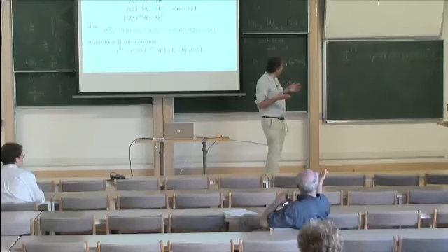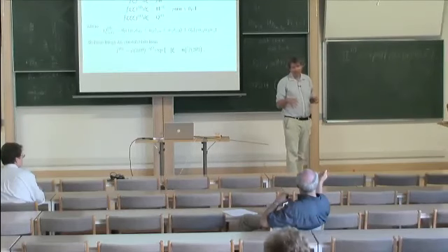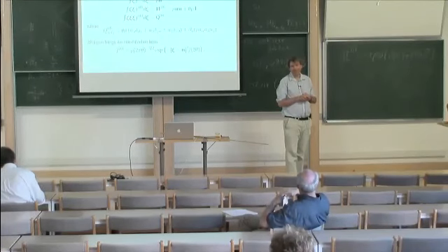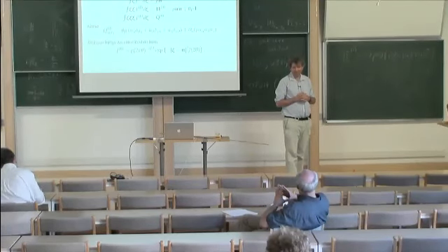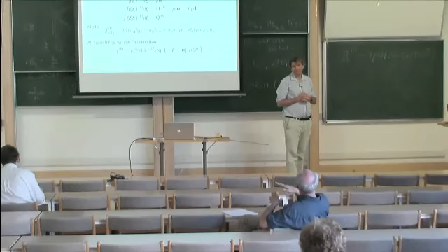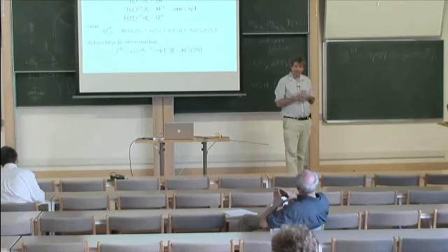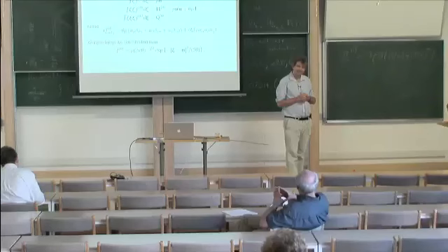No, but if I'm trying to do incompressible Navier-Stokes, I can dial down my Mach number, and that has the effect of dialing down tau. I know there's a small correction, but I can make that small correction as small as I please. So I can converge to Navier-Stokes. I understand it converges to Navier-Stokes, but for any finite tau, it's not precisely Navier-Stokes. No, and similarly for any finite grid, it's not precisely Navier-Stokes because I've got a spatial truncation error. Right, I'm just trying to understand conceptually.